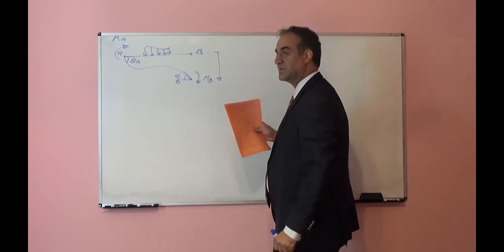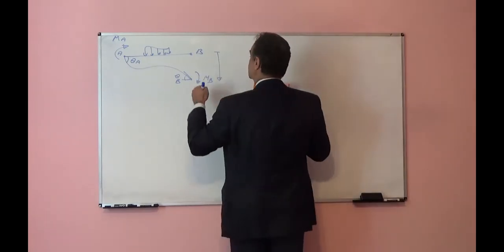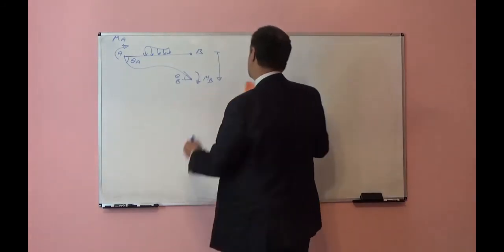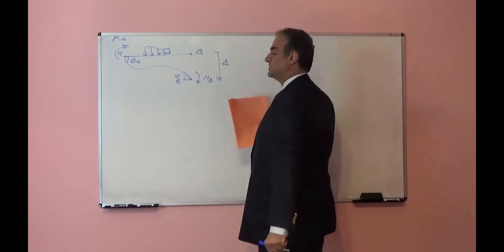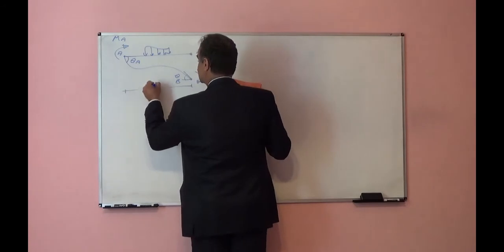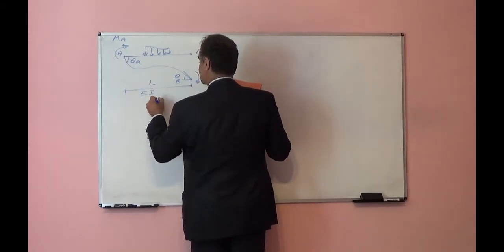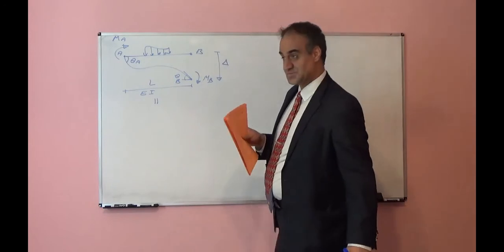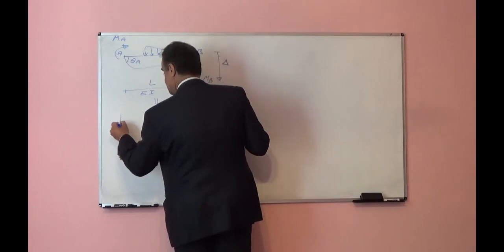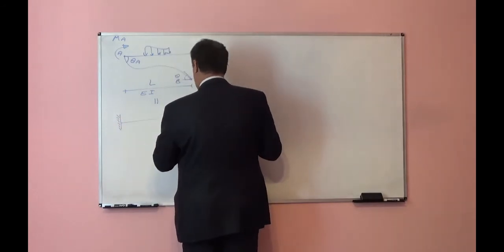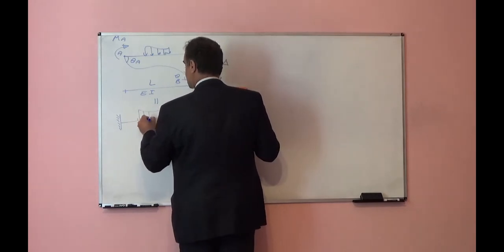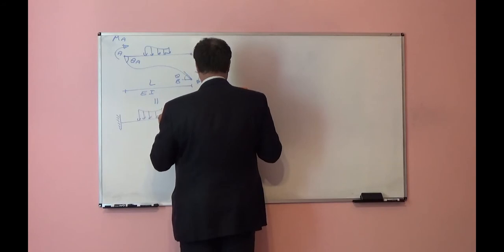A with respect to B, they will have a distance which is perpendicular to the initial direction of AB. In general case, we call that delta, lateral deflection. The initial length is L, EI is constant. If you remember, with superposition, I divided this system into 4 simple systems. One of them was two ends fixed, subjected to external load such as Q.